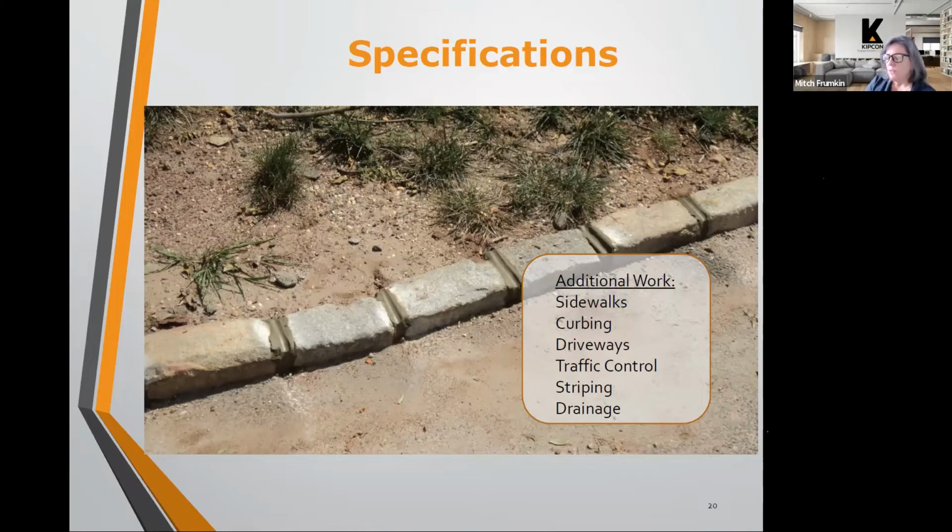So you have the visual of water running through the gutter, but it's meant to do that. It's meant to be conveyed over the surface of the pavement to the catchment where it gets carried away. So there's a perception that there's now a drainage issue because of the new pavement, but that's not the case.